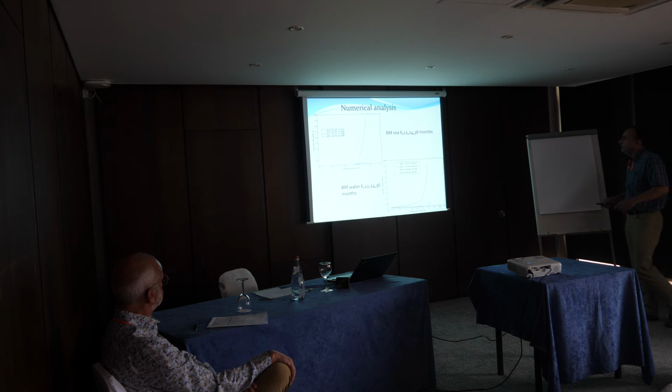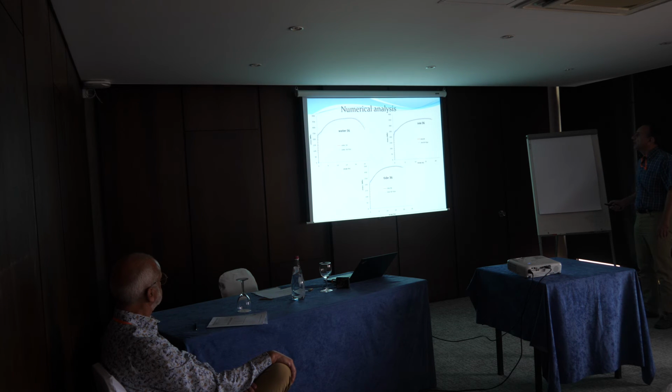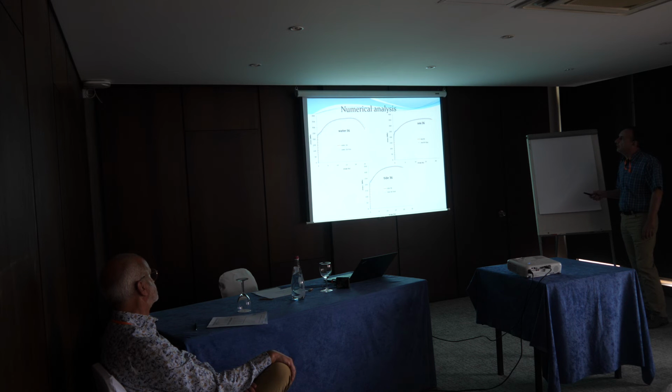We developed these diagrams first and then the results, because the end of these diagrams are the criteria for ductile initiation. So we have here all these time periods in different corrosive environments, and also for the heat affected zone and the weld metal after 36 months. In the tensile test results, the orange is experimental, and the blue ones are numerically performed tensile tests. The failure happened in the base metal in our cases.